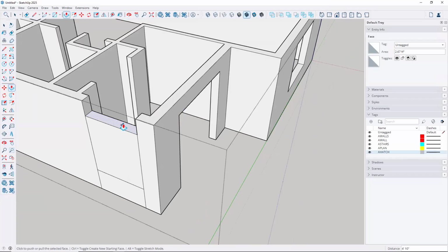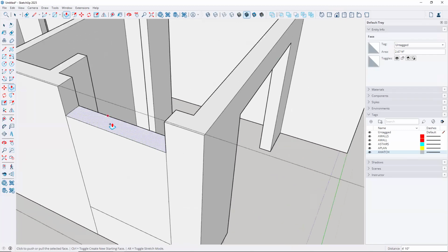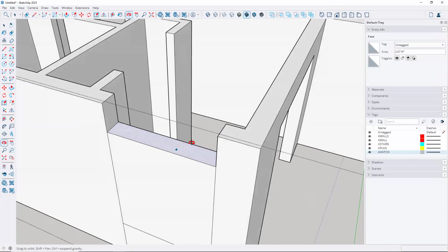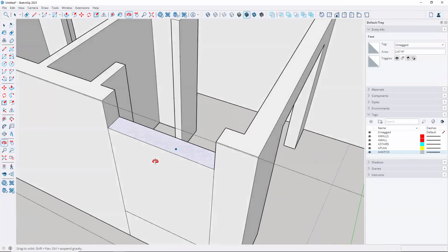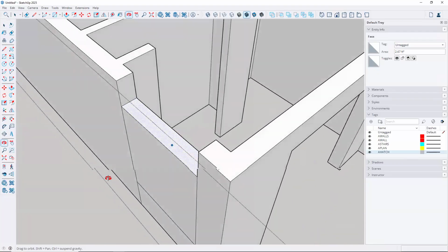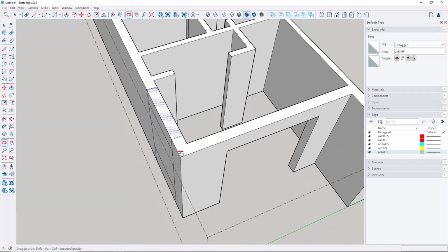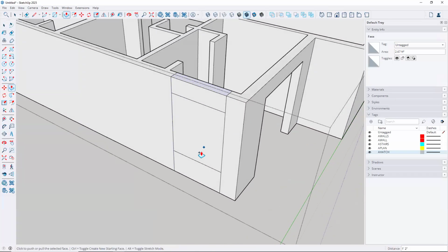And then because I still have the plus sign there, that means it's going to generate another copy. So I'm just angling this in such a way so that the boundary there of the group doesn't really get in the way. So I'll do it like this. I click and see how it's making a copy. And I'll just click on this endpoint over here like that. So I started at the base and I basically did a push pull 2 more times and I tapped the control key so that it makes a copy.